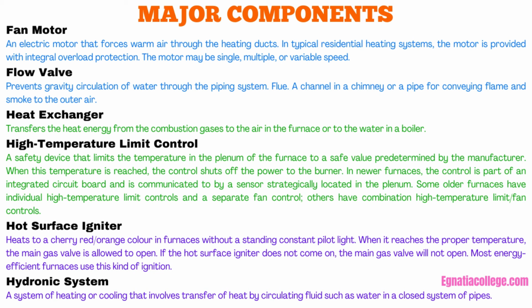In newer furnaces, the control is part of an integrated circuit board and is communicated to by a sensor strategically located in the plenum. Some older furnaces have individual high-temperature limit controls and a separate fan control, others have combination high-temperature limit/fan controls.